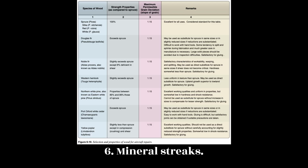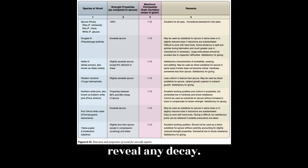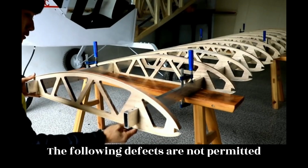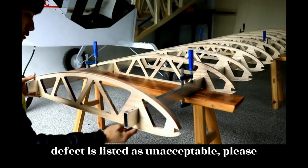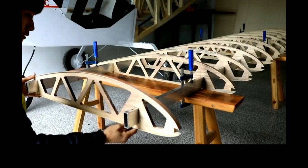6. Mineral streaks. Acceptable if careful inspection fails to reveal any decay. Defects not permitted. The following defects are not permitted in wood used for aircraft repair. If a defect is listed as unacceptable, please refer to the previous section, Defects Permitted, for acceptable conditions. End of page 6 to 7.